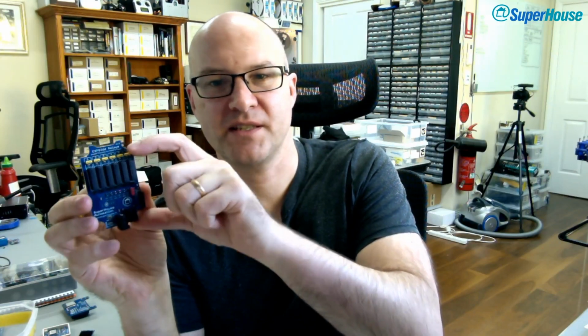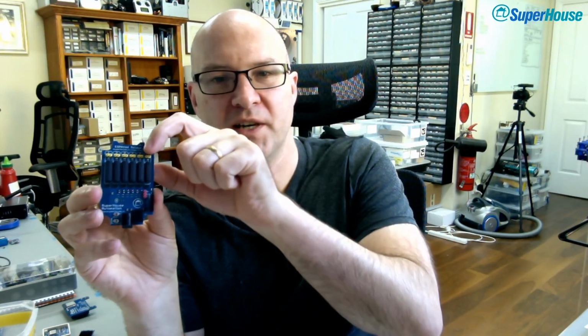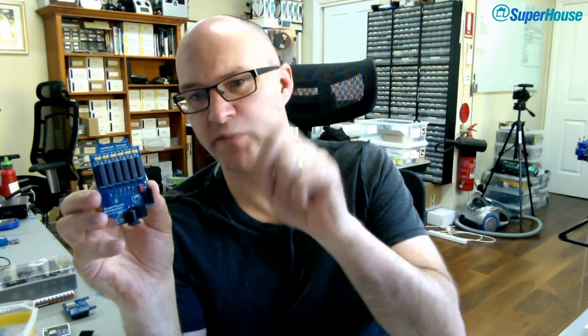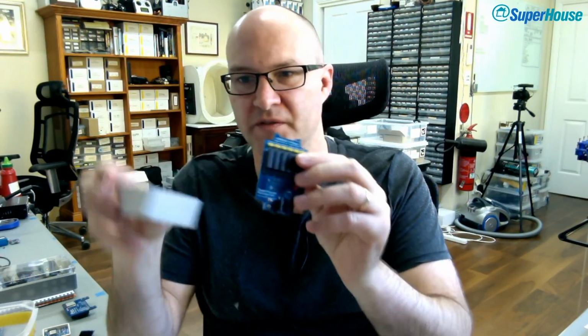Now this particular one, this version just has MOSFETs, so it uses open collector outputs, and that's fine if you are running a common ground to whatever your target controller is. This version has reed relays, so each of these is a dry contact output. You can wire that across the contacts of a button for a transmitter, and then when you fire the relay, it's as if you press the button on the transmitter. And both of these things fit into the same case. And that is the sort of project that I use these templates for.